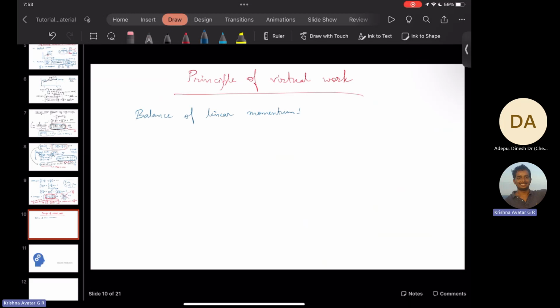So in that case, what we had is rho x double dot vector is equal to divergence of sigma, which is the Cauchy stress tensor, plus b vector, which is the body force vector. In this particular set of lectures, we only deal with static problems. It can be done for dynamic, but having the dynamic term makes the expression a bit complex, though that does not change the philosophy. The philosophy still remains the same. So in static formulation, we'll have this term to be 0.